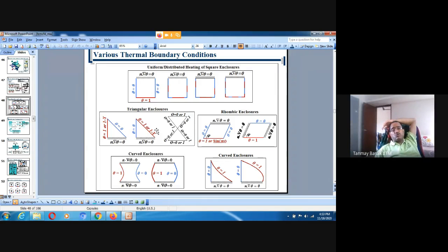You can see that if the solar heat is radiated here, and if you have a PCM, phase change material, that can keep a constant temperature, can we improve the heating with the triangular domain? We can have this kind of triangles, and sometimes within the entrapped triangle, the fluid is flown within some of the tubes, and with this entrapped triangle, you can have some other fluid so that you can extract heat before throwing out the effluent or pollutant fluid.